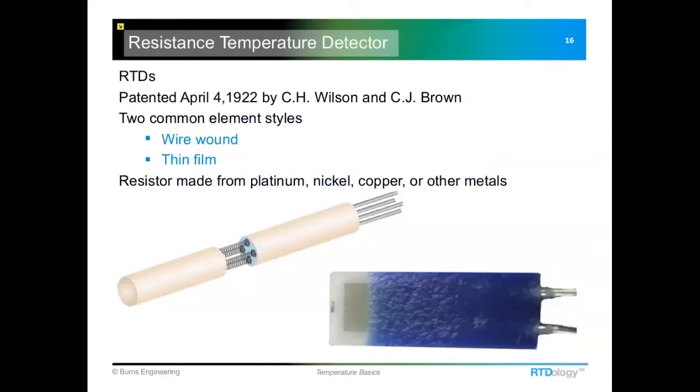One more thing I wanted to mention on this slide. A couple of very common styles of platinum resistance thermometers, PRT, which is another term. This would be a wire wound or a coil style, and this happens to show a dual sensing element. This little cutaway shows the coils of platinum wire inside this ceramic mandrel. These are typically about 1/16 of an inch in diameter. So you can imagine it's all very tiny stuff, and all the assembly is done under a microscope.